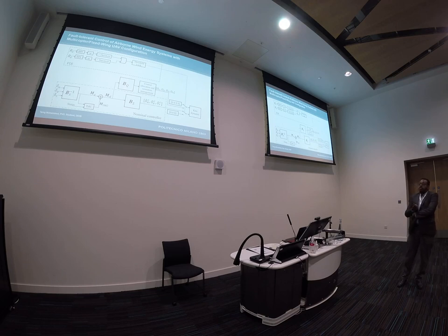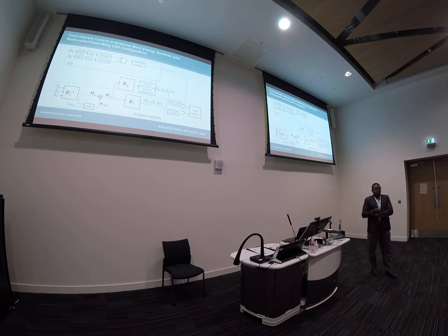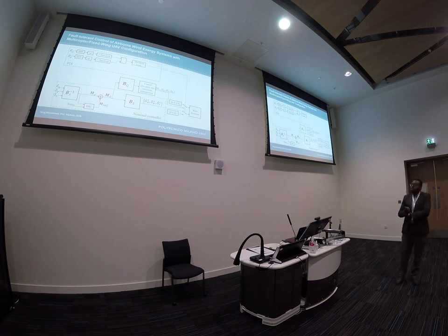Here we have a fault detection and isolation algorithm. We compute the residuals about Rx, the longitudinal axis. We also compute the residual about the yawing axis, as seen in Rx and Rz. And if any of these residuals cross some predefined threshold, we will isolate the surfaces completely, and we will use the quadrotor to take control, as you see here.